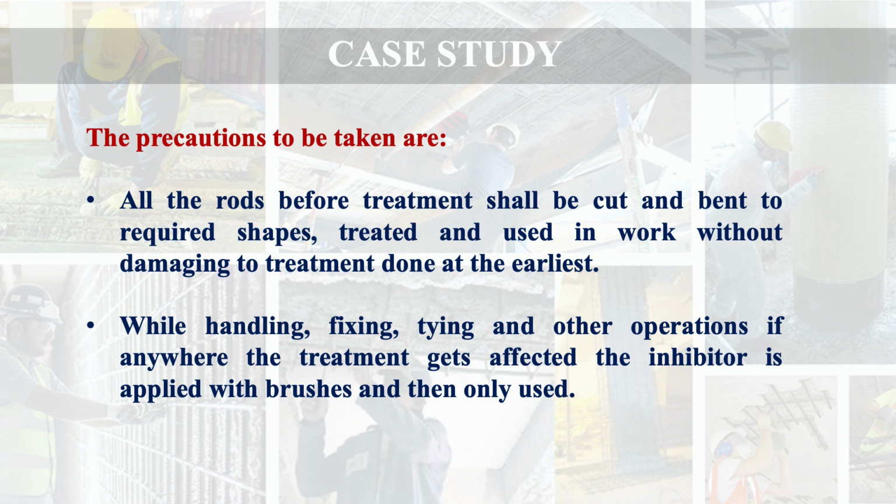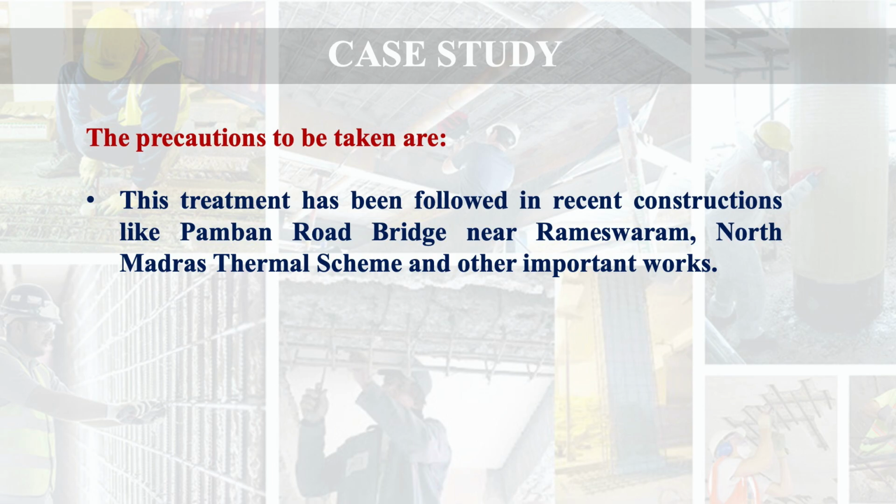Because if you are cutting or bending the reinforcing bars after treatment, then it will destroy the protecting layer. While handling, fixing, tying and other operations, if anywhere the treatment gets affected, the inhibitor is applied with brushes and then only used. This treatment was followed in constructions like Pamban Road Bridge near Rameshwaram, North Madras Thermal Scheme and other such important works.